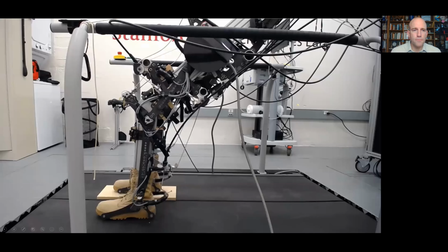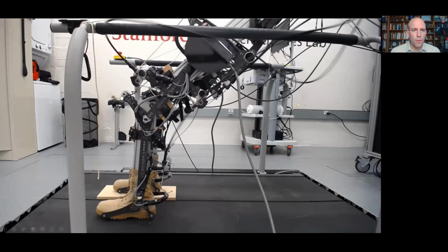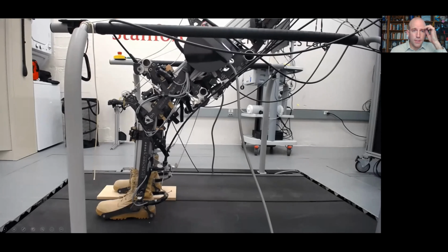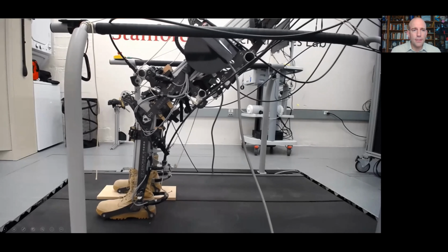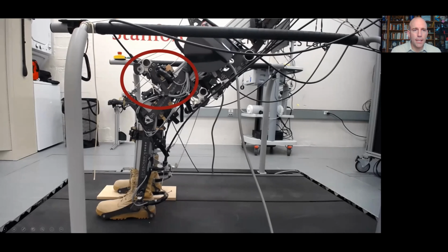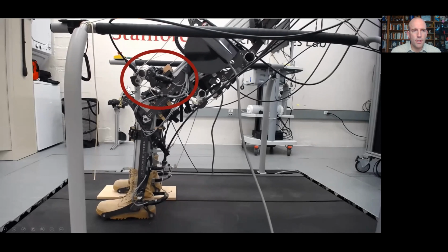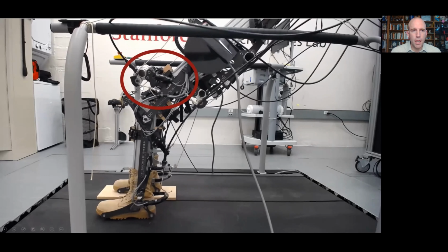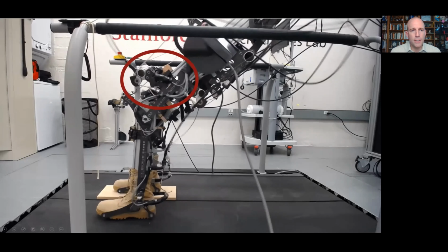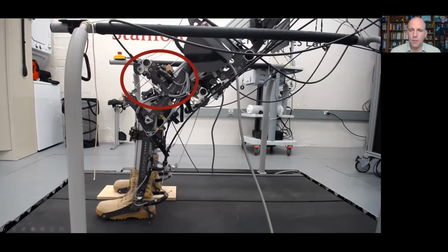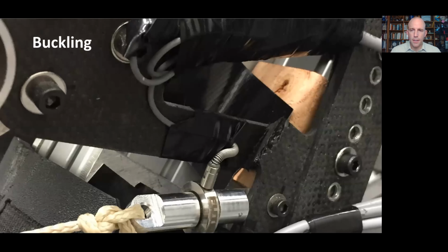Now, buckling is something that we see in the laboratory as well. And here is an example from a full leg exoskeleton where we're applying a test, stepping up a very large force, 250 Newton meters of knee extension, and something breaks. And you can see it happening in here. There's a big tension force here at the end of this beam, which is essentially a beam in bending. So the top part is under tension and the bottom of the beam is under compression. And that bottom part under compression buckles. And the way it buckles is out of plane.